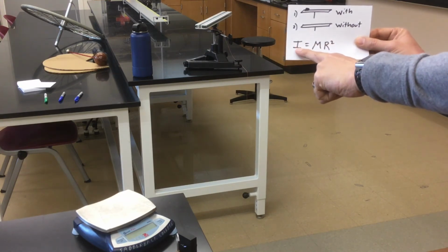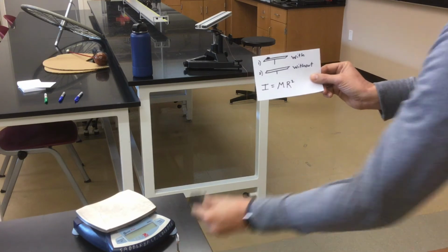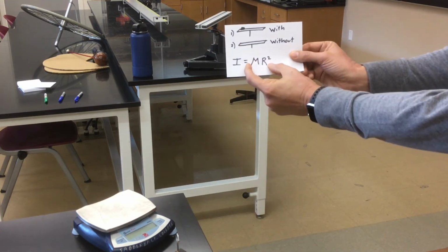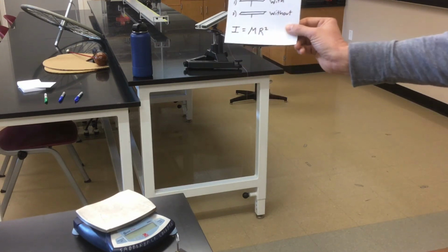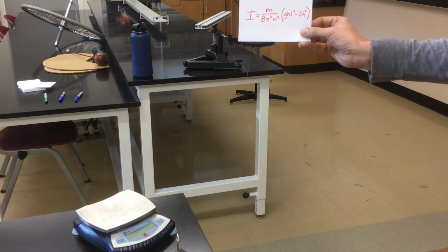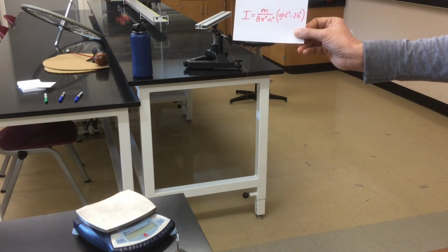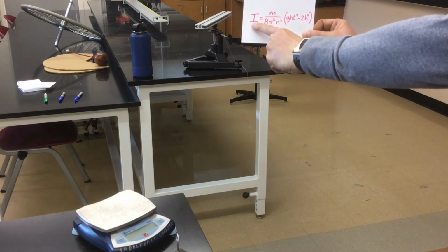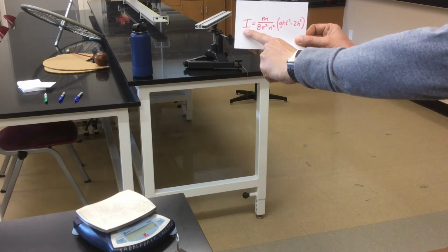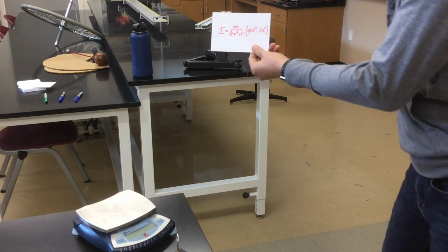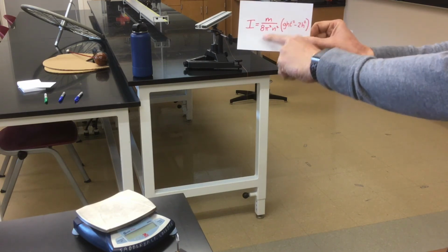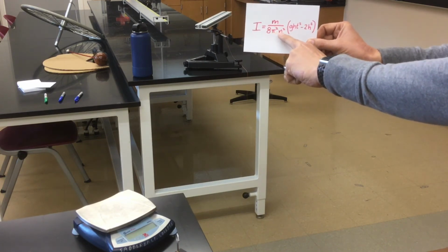In the end, we're going to try to prove that the rotational inertia of just this object by itself adds an additional value of capital Mr squared to the system. So you need another formula. In another video, you'll find a setup for how you can derive this equation that says the rotational inertia, whether it's with or without the additional point mass, the rotational inertia of this compound system can be calculated by taking the 150 gram descending mass, divided by 8 pi squared times n squared.